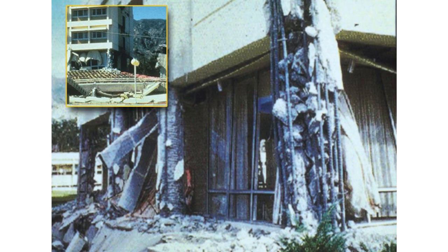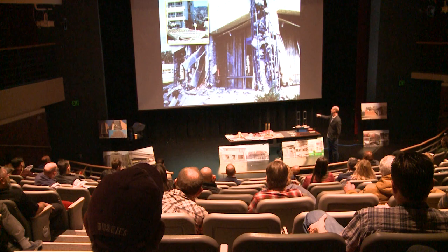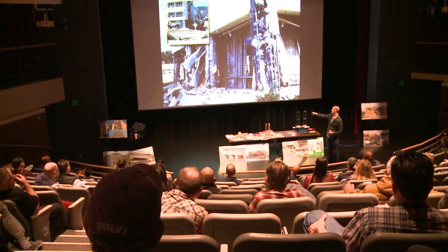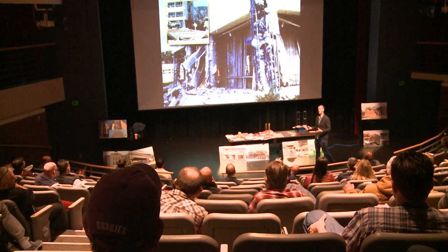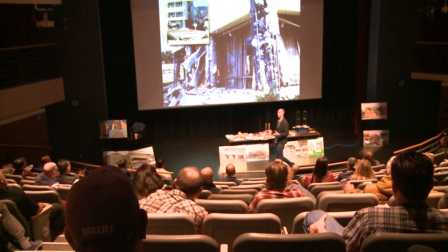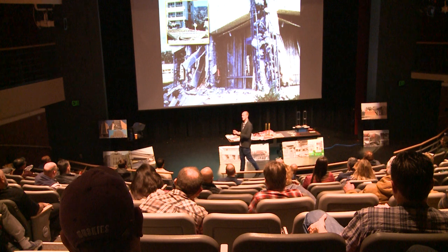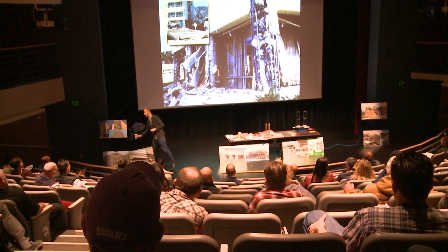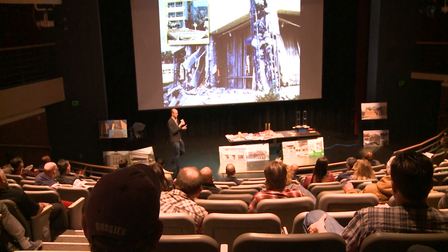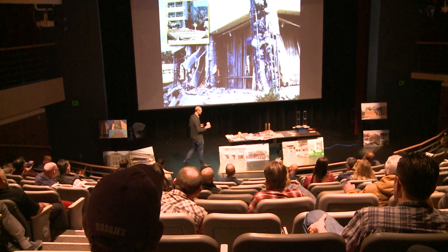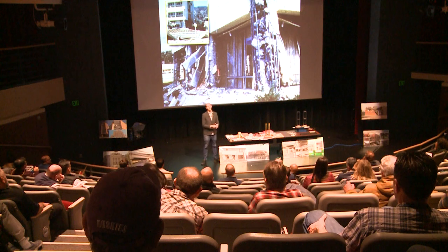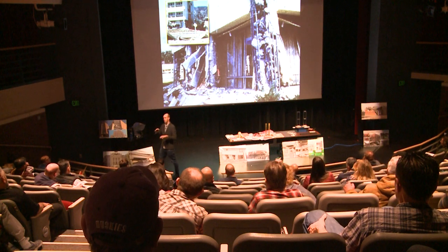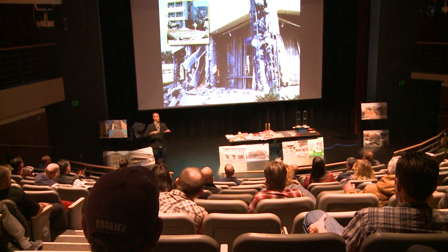All things being equal, you have a corner column, interior or exterior regular column, and then an interior column. All things being equal, which one are you more concerned about? The corner, the exterior, or the interior? I heard some corner. So say they're all equal, they have the same stiffness, they all took the same lateral load. Which one is taking the most gravity load?